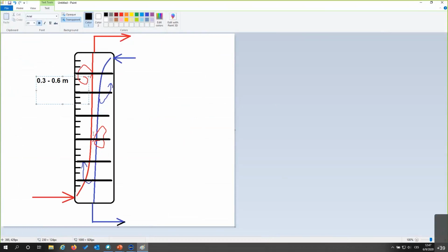And generally, if you have taller increments, that means that we assume more back mixing, more deviation from the pure counter-current flow behavior. So that's the reason why it's safer to use fewer increments and taller increment height.